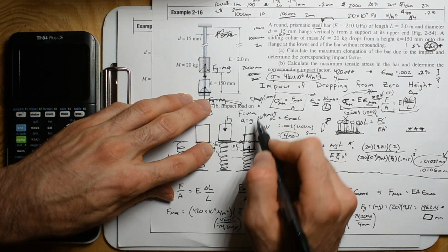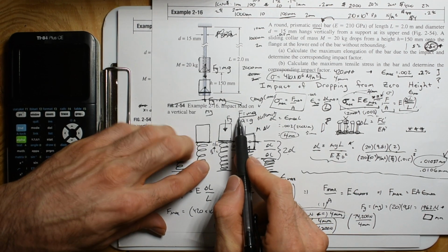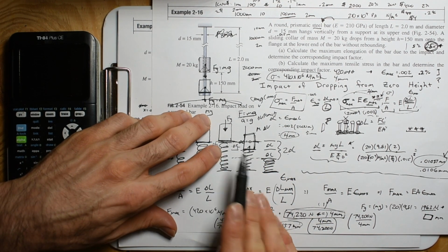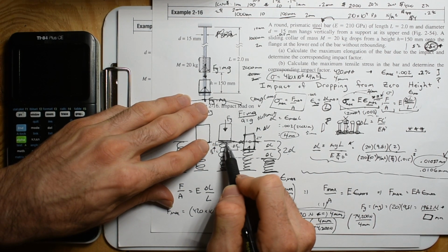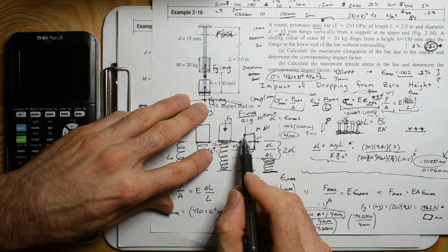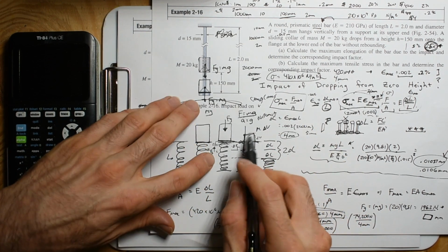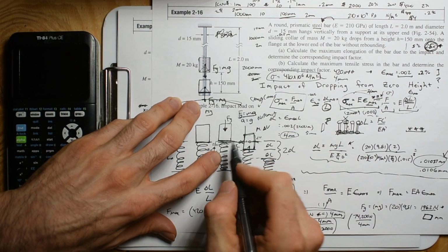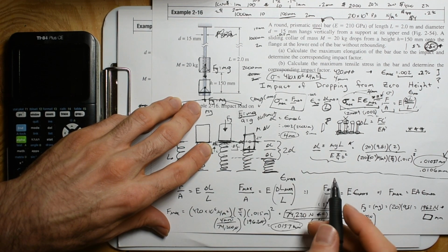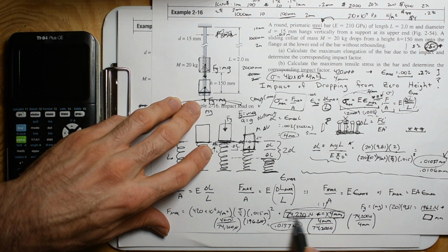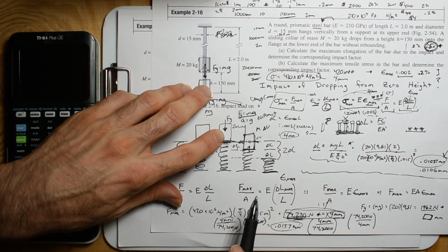And if you have some sort of velocity, the only thing, F equals ma says, the only thing that can change that velocity is a force. And that's what we see. The spring does provide a force, and it has to slow that velocity. But the spring, when it starts off, has a very small force, so it can only change that velocity. So you can model it where the force of gravity is going to be bigger than the spring force for a small displacement. But you can see that if we have a displacement of 4 millimeters, we can generate a huge amount of force compared to just the 200 newtons that's generating from that mass.